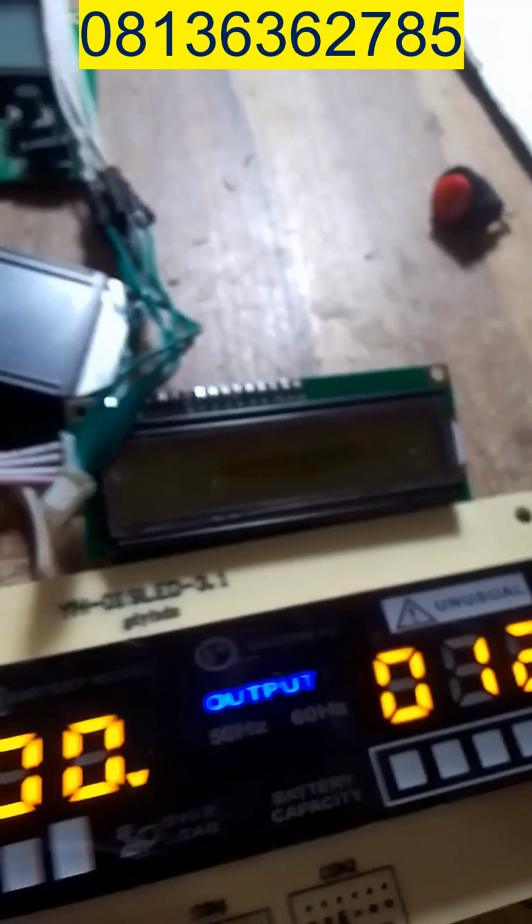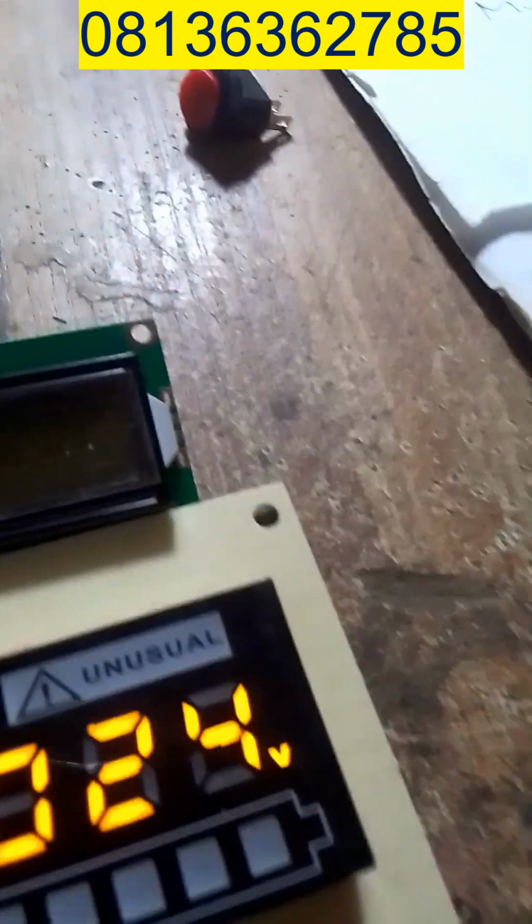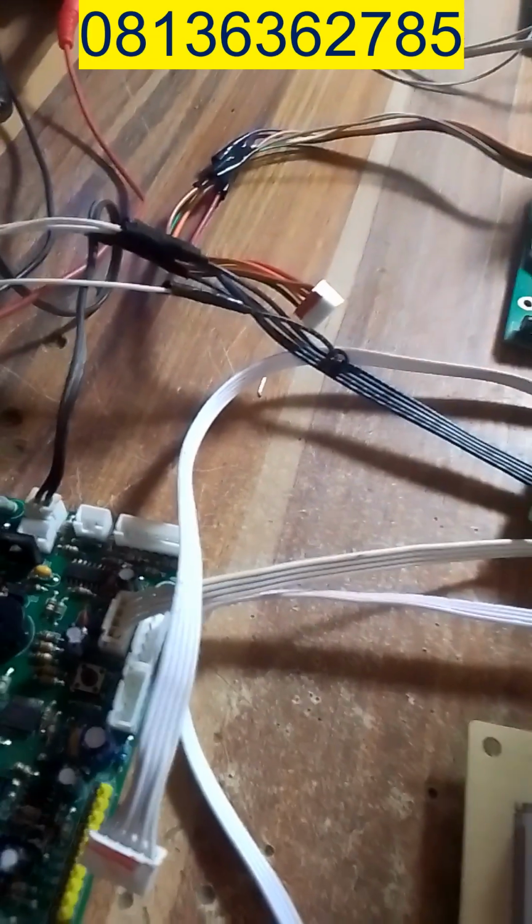So it means that if I exit diagnostic mode now and I want to power the board, I must use a 12-volt system. That's what it means, and it will be displayed on all the LCDs, on the output, during the diagnostic mode. So that's just it concerning changing the voltage. I've changed it again and returned to 24. So you can select the voltage of your choice, maybe 12 volts, 24, 36 or 48, depending on the battery system you want to use with the inverter.